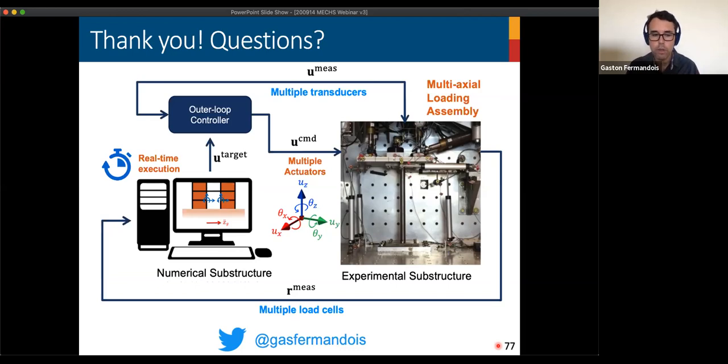In this framework, we only consider a linearized version of the model, and we design compensators based on that linearized model. But even though the feedforward is designed for this linearized version, if there is some uncertainty in the model that is not captured, we still have this second layer in the compensator that gives enough robustness to the controller.